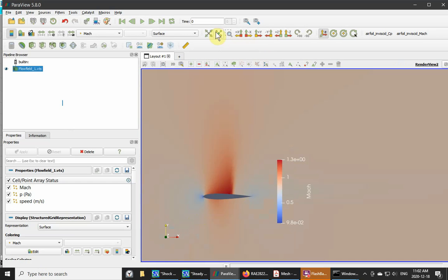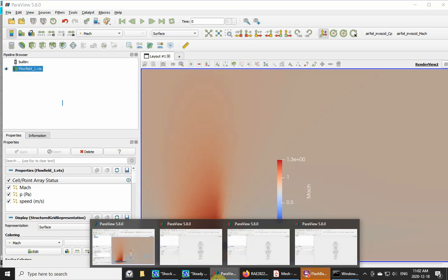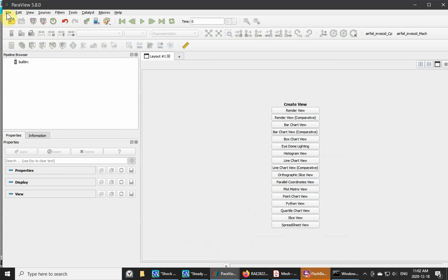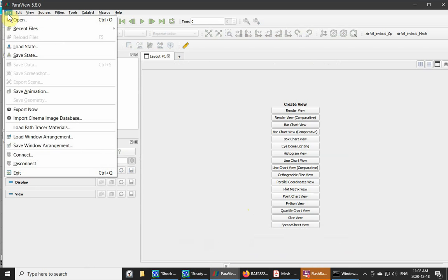video. And simply zoom in here, and here you have the subsonic flow being accelerated to a supersonic condition on top of the airfoil, and that is terminated by an attached shock front, and it's a fairly fuzzy interface because of the coarse grid. This is shown more clearly by inputting the pressure profiles.